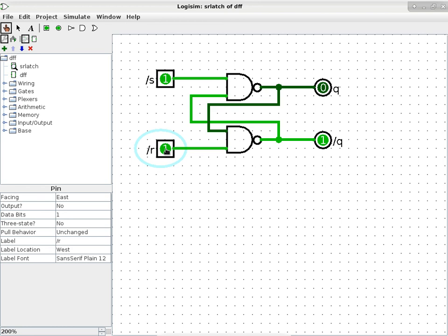So as a computer, actually that probably wouldn't be an issue because you would never have it be exact. Well, that's a very good question. So the question is, what if one gate takes a longer amount of time to update, and the other one doesn't take as much time, right? In that case, it would actually settle in a particular state. It wouldn't oscillate anymore. So how does your computer prevent this from happening? You simply do not go from both inputs of 0s to both 1s at the same time. That's the bottom line.